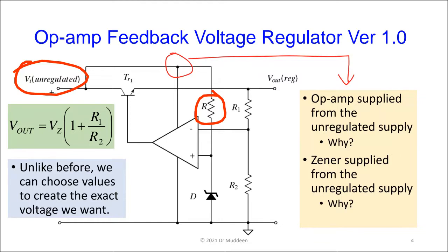So sometimes it's good to think and stretch your brains. Once you supply the Zener from the unregulated supply, you have to cater for the worst case in the unregulated supply. As we saw yesterday with our 1-volt ripple and our 15-volt AC supply, that was something like 20 volts. So it was going between 20 and 21. You have to cater for that.